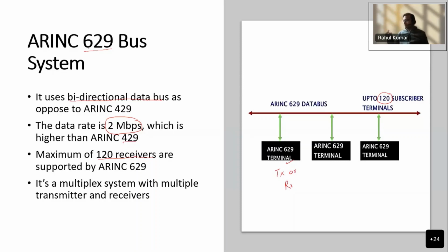For transmitting or receiving data, each terminal will require a token. Once it has transmitted its data, the token is then passed to the next terminal. Like that, one by one, each terminal will either transmit or receive the data, and obviously fixed time is allotted to each terminal.